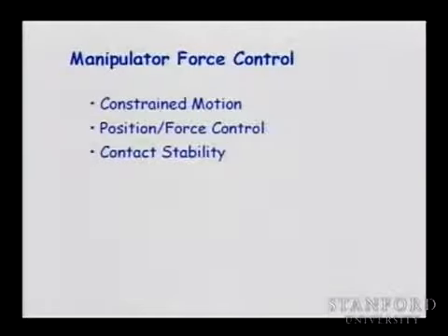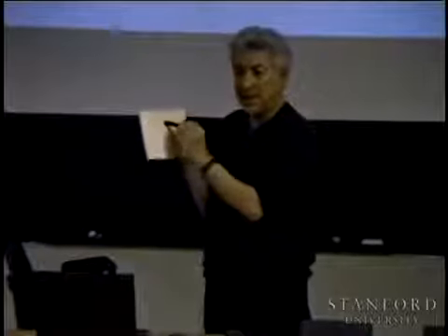Finally, we need to deal with the problem of controlling contact. So moving in space is one thing, but when we are going to move in contact space, it's a different thing. Applying this force puts the whole structure under a constraint, and you have to account for these constraints and compute the normals, so as to find the reaction forces in order to control the forces being applied to the environment.